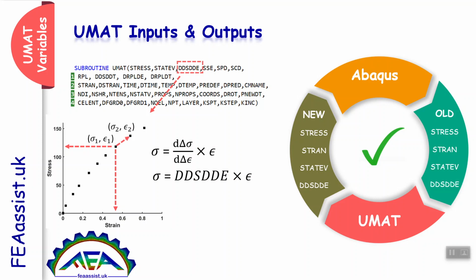For all variables, based on your equation, you need to understand well the nature and the source of the variables. For example, in the elastic regime and for elastic problems, the elastic stiffness matrix is the DDSDDE matrix.